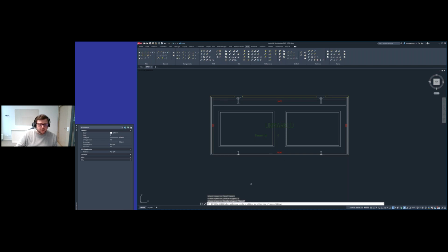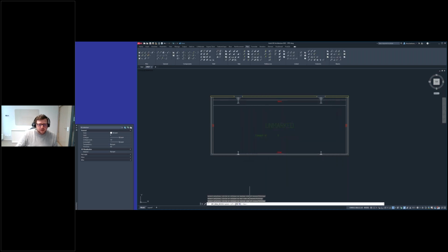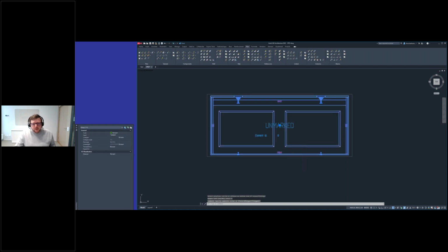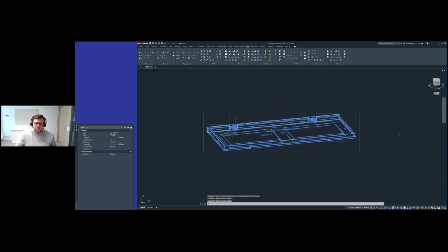So first it says polyline of the bottom side, the big one here, then the top side, the smaller one. And then I can repeat it for as many recesses that I have. I do 2 here and say okay. Then I want to update my lifters, and voila, it adds these polygon recesses in the bottom.